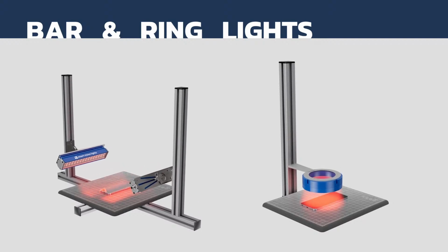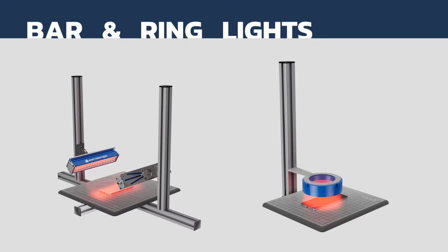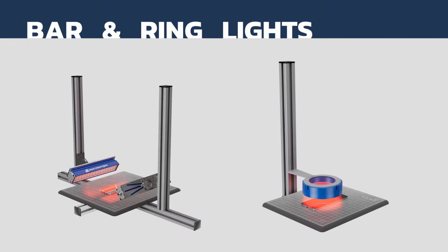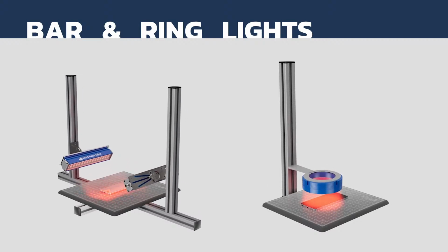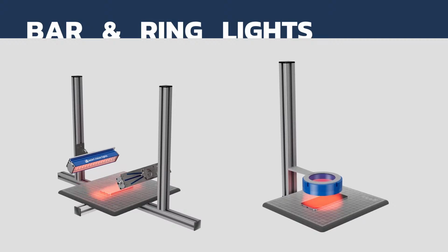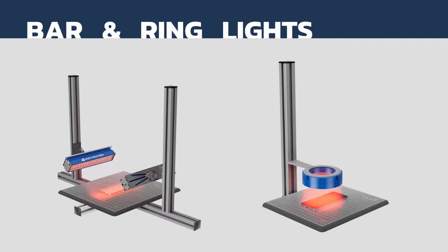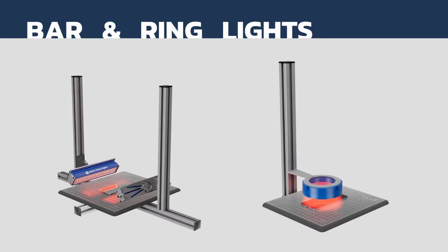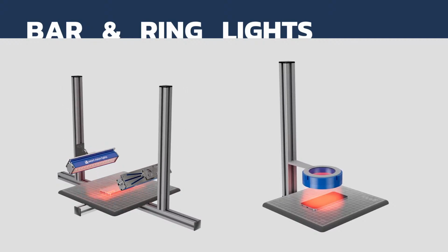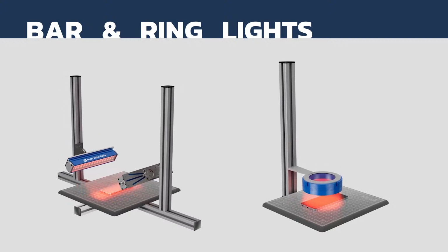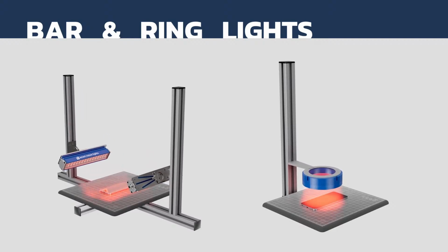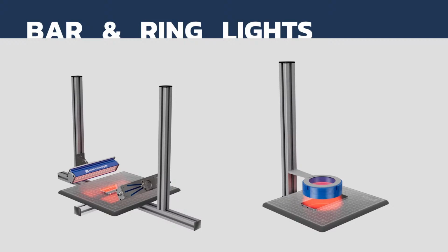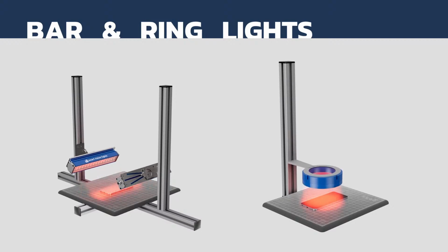This ring light has a blended surface which emits at varying angles. So near the center of the ring, it's emitting very perpendicular and near the optical axis. As it moves towards the outside of the ring, the angle is getting steeper and steeper till it's near 90 degrees at the opening of the light or the edge of the light. So what happens is as that ring light moves up and down, you're getting dark field effects when it's very close and more of a bright field effect as it gets further away, and a combination effect in between.